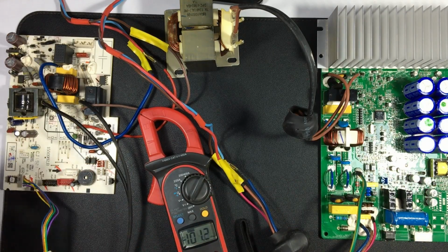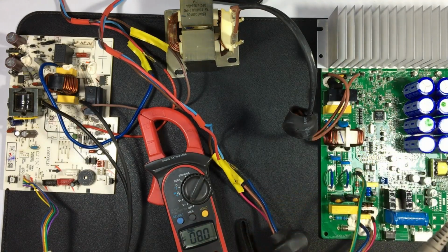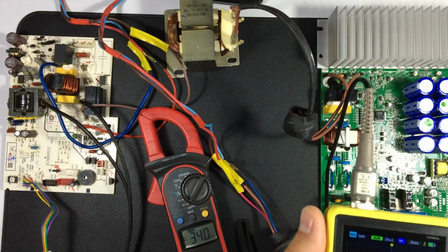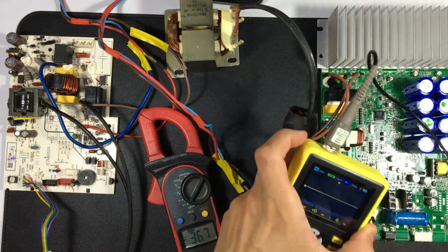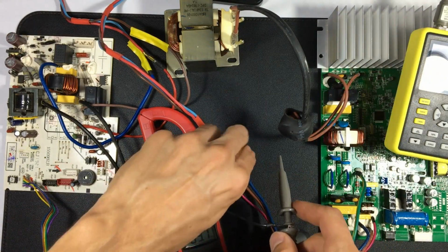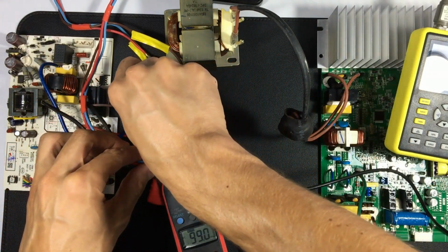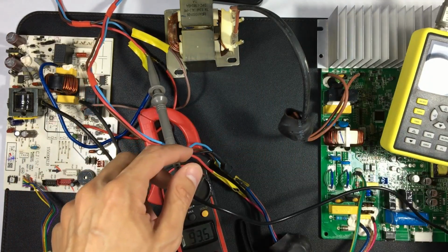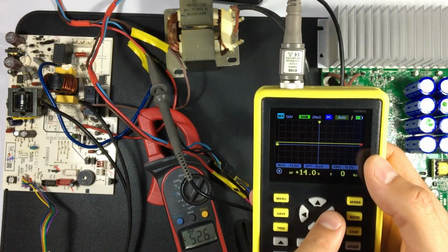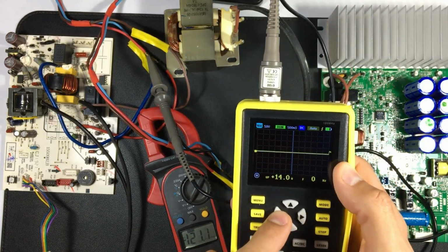That's exactly what we're going to see with the oscilloscope. There are units that communicate up to 50 volts, so we have to activate 10x. Tell the oscilloscope that we're going to use 10x and place the negative test lead on N and the positive test tip on S. We're going to zoom out so we can see what's on the screen.